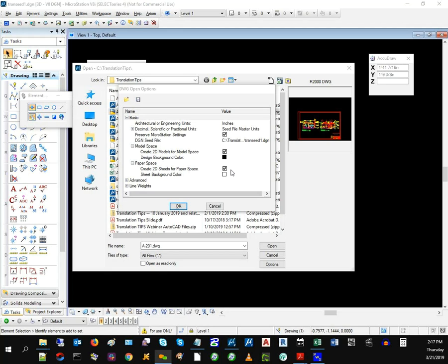And this is where that problem that I mentioned earlier, where things in references aren't quite matching the right spot they should, or other things in the design files you open that were DWG files that you just saved as DGN files, where things aren't quite in the right place, this will handle that.